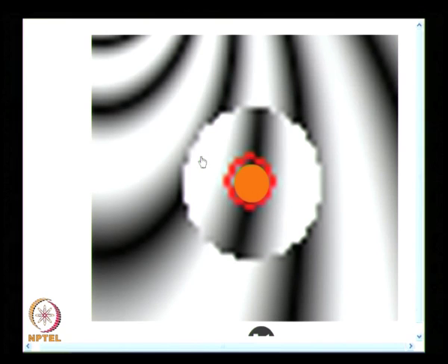What we have made observation is a higher fringe order has moved and occupied this position. So, that means what I have done is I have done the compensation in a manner, whatever the fringe order is 3 minus, in this case it is the fringe order 3. So, 3 minus that compensation will give the fringe order at the point of interest.